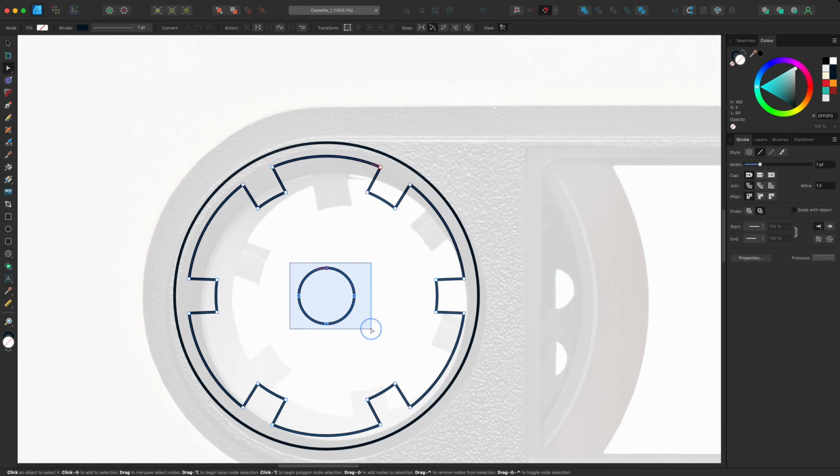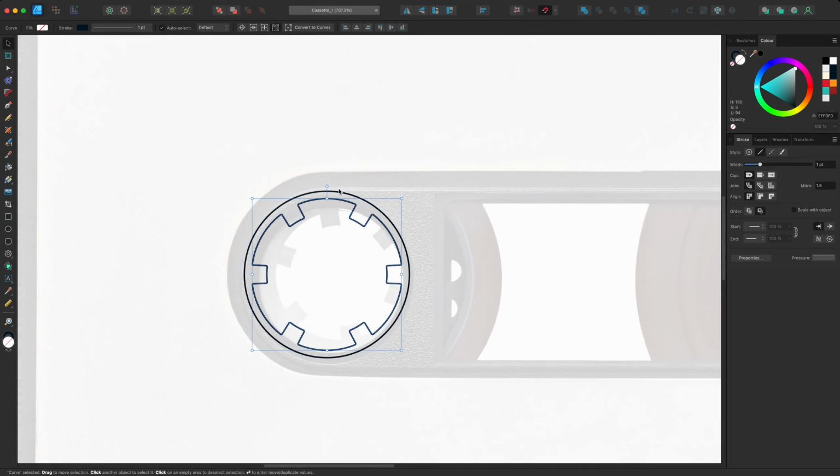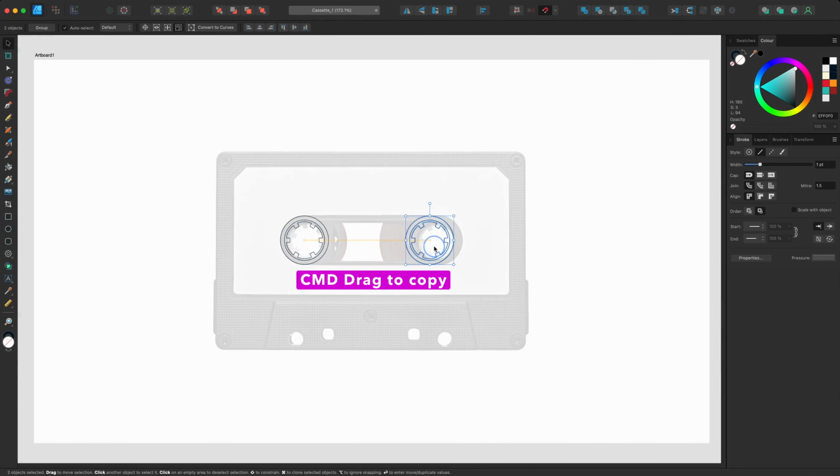I don't need the path in the middle as I intend to create one shape using a Boolean subtraction command, so I simply select the outer object, then select the inner object, and then use the subtract command to create one piece of geometry. Now, using the shape as a snap candidate, I create another circle, and after selecting everything, I duplicate it to the other side, and then group them together so I can align them both to the centre.